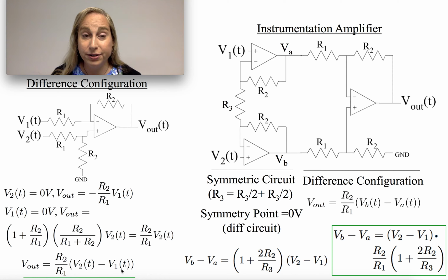So this is a very, very useful technique. It's important to notice that this is a resistor divider to handle the fact that I've got 1 plus R2 over R1, to match that with the natural minus R2 over R1 of the inverting configuration. So this works out really well, and you say, great, what else can I build?